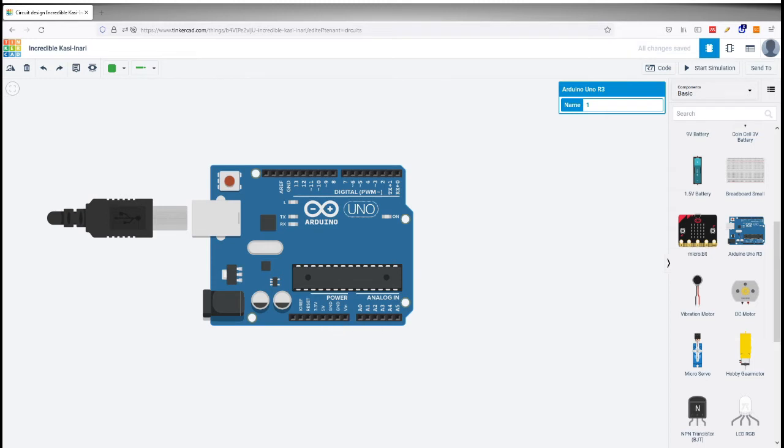So if you want to connect a small motor which is working on 5 volt, you can take the supply from this pin. If you want to connect another device which is working on 3.3 volt, you can connect it from this pin. Then the corresponding grounds are here. You can use any one of the ground pins. On the other hand also you can see one ground pin.